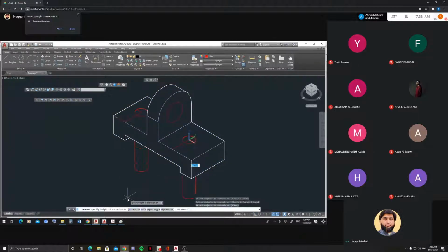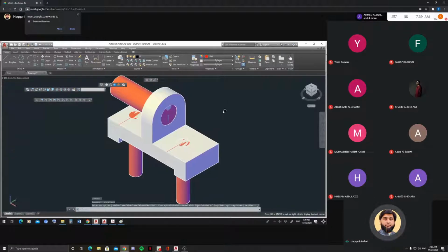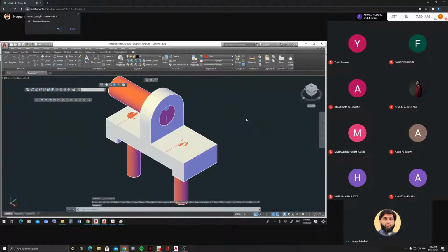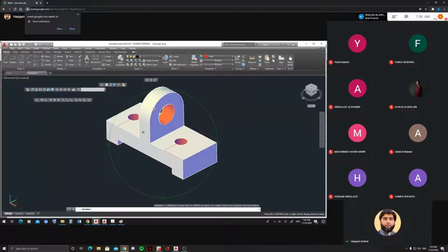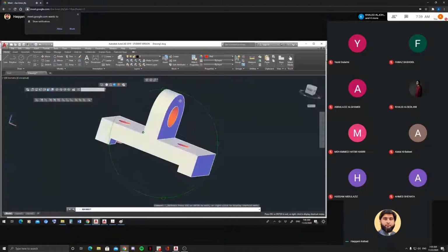Enter. Okay, like this. And I will extrude the middle circle. This one. Okay, this direction, because it should not come this direction. It should go the other one because I need to subtract. Now I can go for subtract. SUB. Click the main body. Enter. Now you select this one, and this one at a time because everything is same. Now you got the holes for this one.